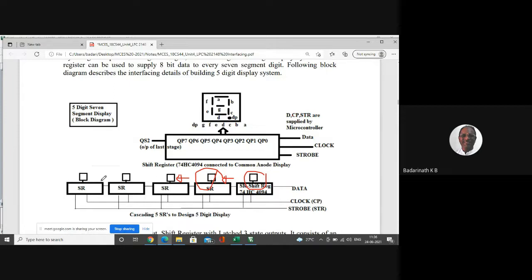So now we'll be writing a driver code. What is a driver code? Driver code which drives this 7 segment display. We will break the problem into very small things. Now, what is the logic required to push 8 bits of data into one shift register? That is a basic problem for me. The smallest block of code is this one. How do we develop that code? We will only look into this logic now.